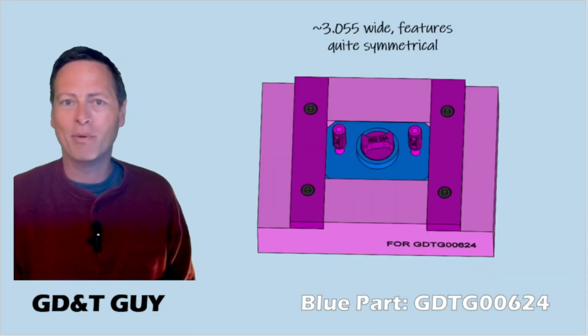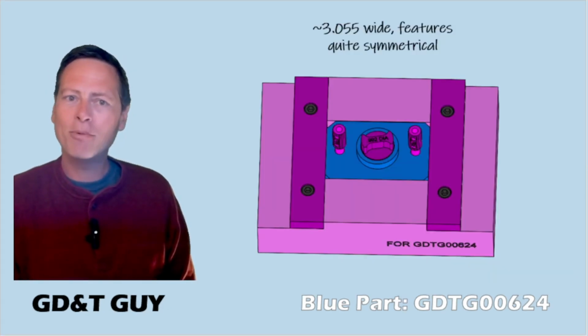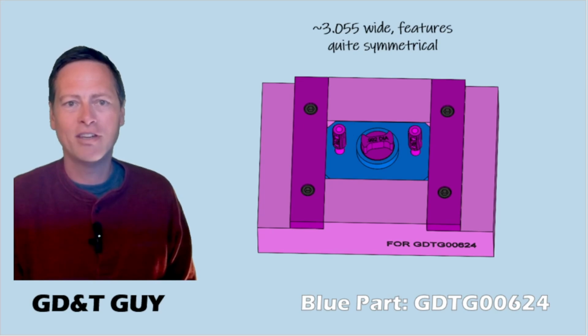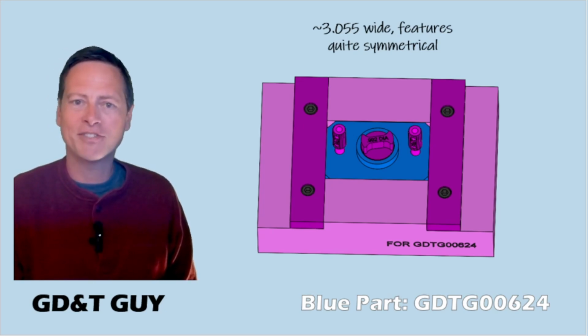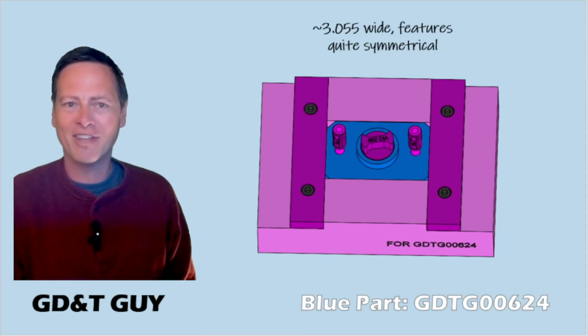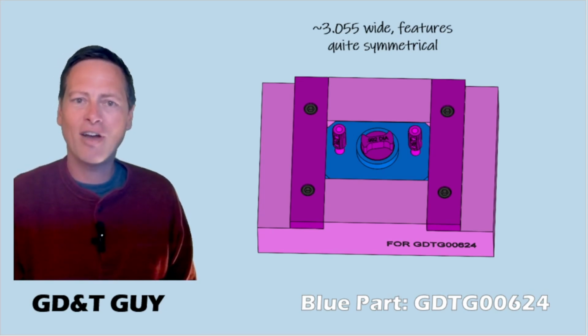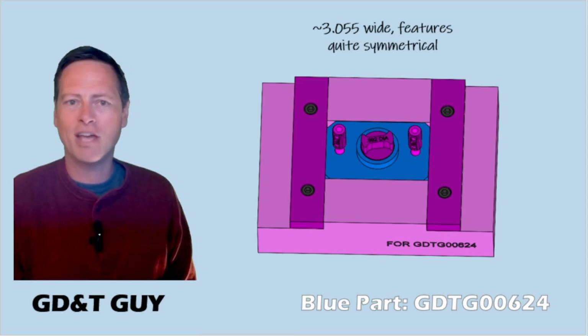We can really see that when we put into this gauge the geometry that is about as wide as it can be, but where the other features are quite symmetrical. And this one is a pass, okay, because the gauge elements can all go together. But you can see how as the datum C feature approaches MMC, there is very little room for asymmetry of the features in the middle.